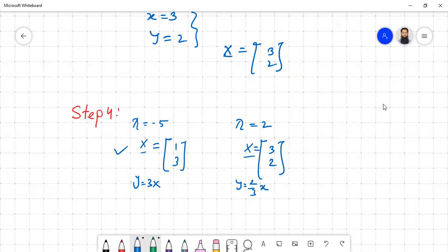Yeah, okay, now in the phase plane, which in this case is the yx or xy plane, you have to find out these two equations for these two cases. But one thing you have to remember is that minus 5 is a pole of the system on the left half plane, and it will give a decaying nature. So basically the line will be converging towards the equilibrium point. In our case, the equilibrium point we also calculated is 0, 0. So this one will be converging towards 0, 0.